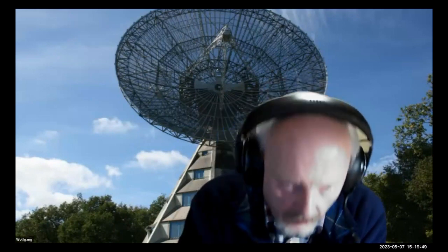Okay, so you recommend, but once you're behind the LNA, you are fine to put in whatever filtering you like. Before the LNA is really critical, and putting in a filter in there, maybe a low loss cavity filter, would be the very last resort in extreme RFI situations.